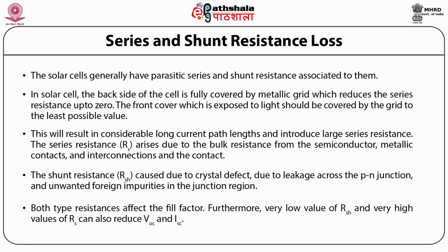Both types of resistances affect the fill factor. Furthermore, a very low value of RSH and a very high value of RS can also reduce the VOC and ISC.